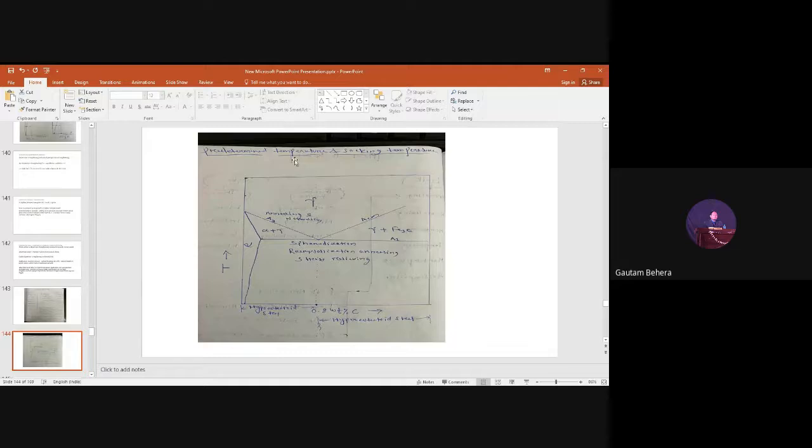Now, as we have discussed many heat treatments, what is the predetermined temperature and what is the soaking temperature? You can see this is the 0.8 weight percentage of carbon. This is the temperature axis, and this is the weight percentage of carbon axis in steel. So 0.8 weight percent carbon steel is this point here, right? Above this point, what is the phase? Austenite. Austenite phase, very good. And this is the ferrite, and this is ferrite plus austenite.